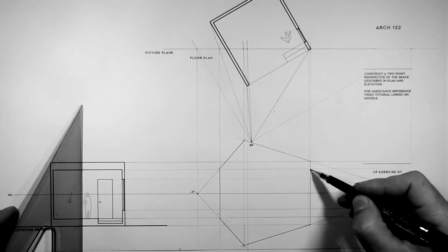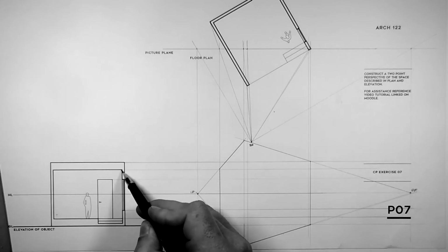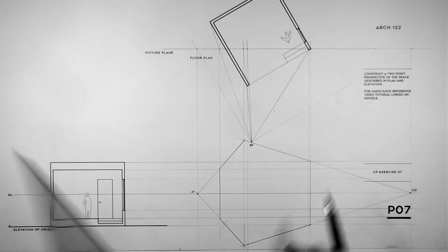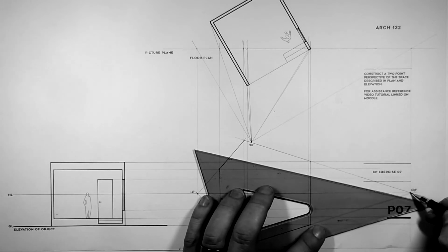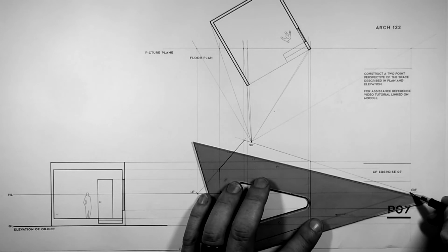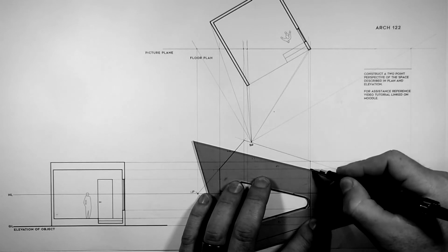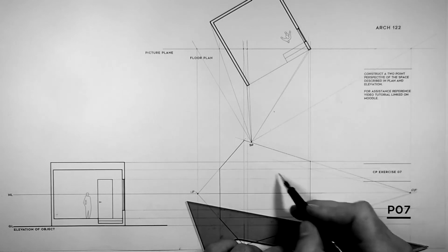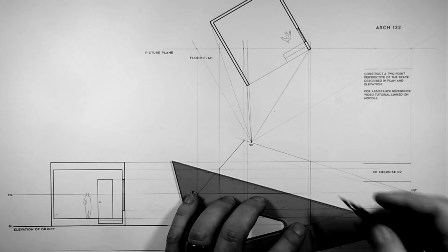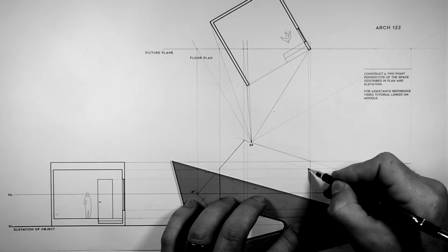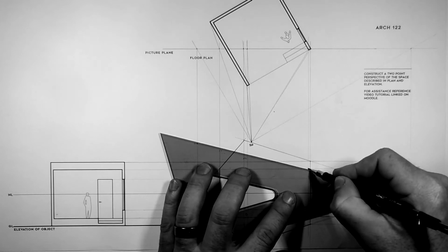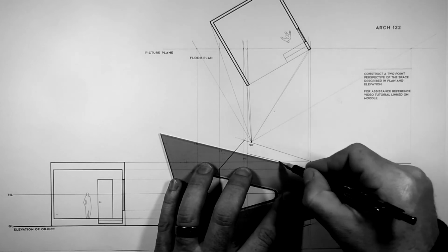So back at the true height line, this outer edge here, where we brought the ceiling height over here. From that point, we can then project the true ceiling height. So again, back to the right-hand vanishing point, and then we're going to pass through that intersection there on the true height line. And so that defines the height of our ceiling. And the ceiling doesn't go all the way to the outside line. It starts with the interior. So it's from that intersection all the way to this intersection here.